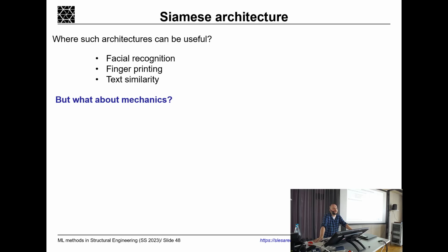Yes, exactly. So using acoustic methods. You can hit a little bit with a small hammer from one side of the wing and measure the response on the other side of the wing. If you have a very solid block, for instance, and you hit it, you will get the same output. But if you have a crack there, you will have a very different signal. So in this case, you really just process the signal.